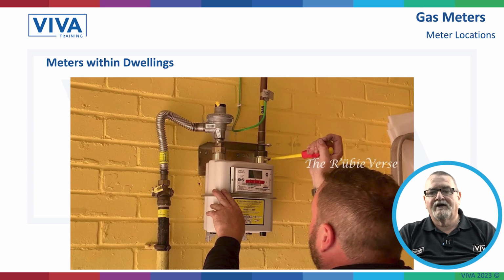The other thing that you can see there, just above where the engineer is removing the test point, we've got a green and yellow lead. That's earth bonding. Now the electricity regs say that our gas pipe should be electrically bonded, and it's got to be within 600 millimetres of the pipe coming off the meter, and it's got to be before the first tee. If it hasn't got that on there, we've got to make the customers aware of that. We'll talk about that later on, but that's something that we've got to be aware of, this equipotential cross bonding.